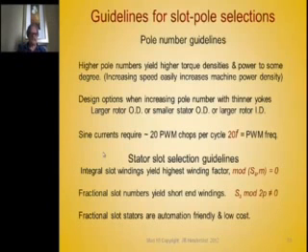You're going to get the same flux. The flux you get is independent of the number of poles, and a lot of people fail to realize that. But remember that's absolute truth, assuming no leakage. There is a caveat in that statement, in that the higher the number of poles, the higher the leakage reactance goes up with increased number of poles. But other than that problem, you don't gain anything by increasing, or lose much by changing the number of poles, other than you need less steel, you need less yoke in the machine.